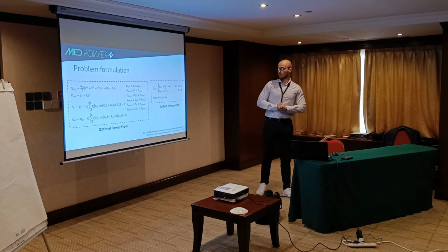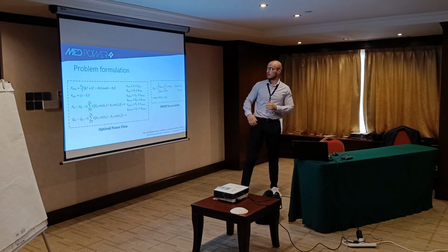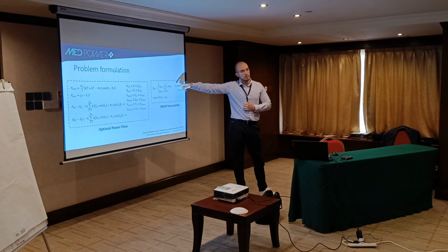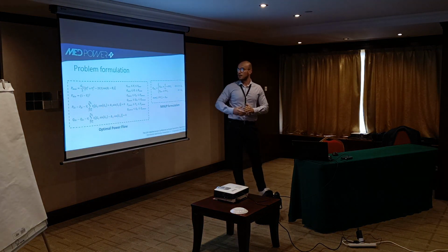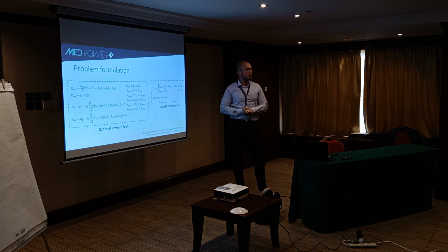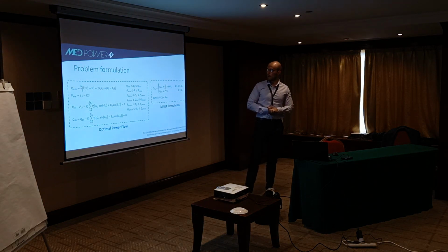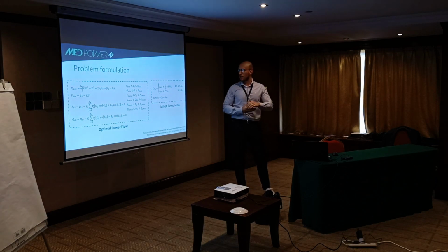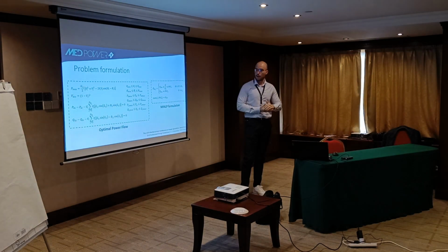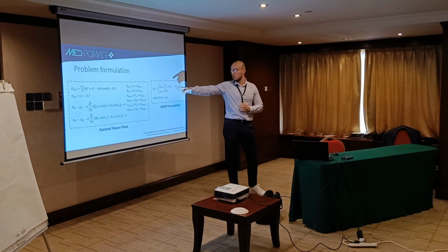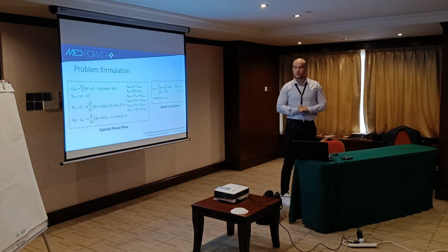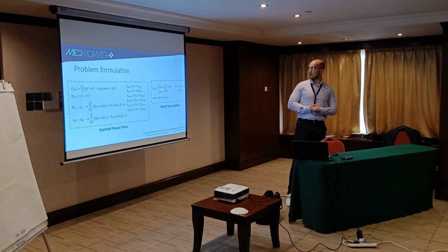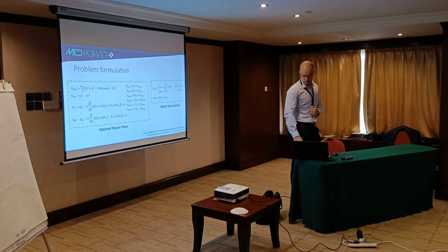As for the mixed integer formulation, we introduced a binary variable, which is used for finding the optimal location, and we incorporated it into the model of the output power of the array. And in order to limit the number of arrays allocated, we chose to put a limitation on the sum of these binary variables over all nodes.